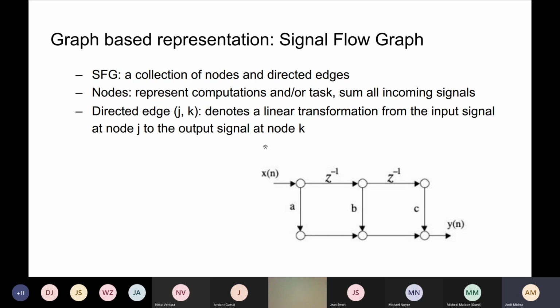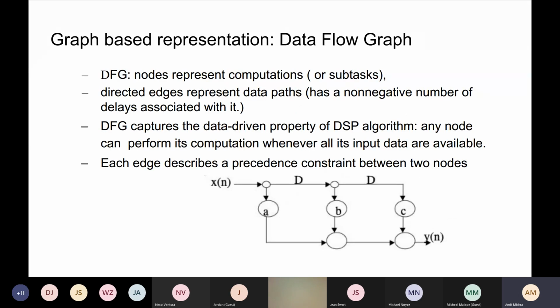Now, again, it's good that it is transforming the block diagram into a network. We can use network theorems, but it's at a much more granular level. Each node is just representing additions. It would be better if each node can represent any arbitrary size of operations, and that's what takes us to the next way of representing hardware as a network.